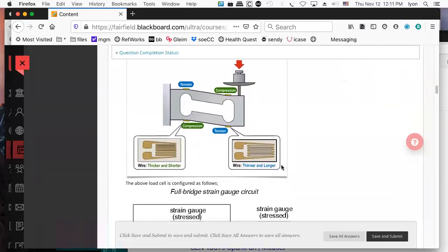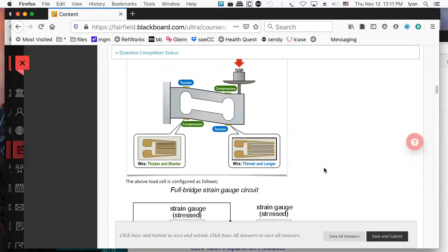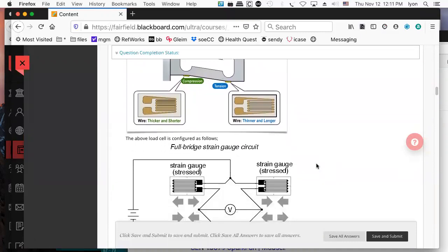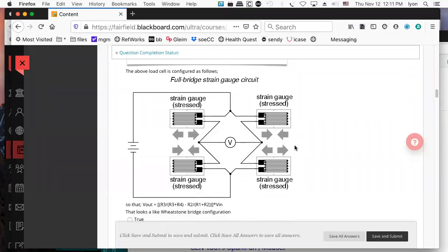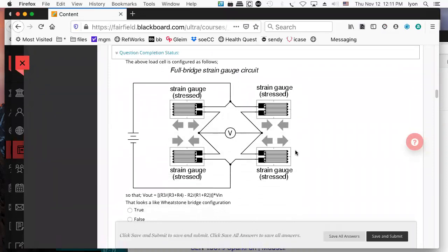And here's the strain gauge again. You can see one part of the flexure goes into compression, where the other part goes under tension. Here we have compression and tension, and we can measure the differences in thickness of the wire, and that changes our resistance.